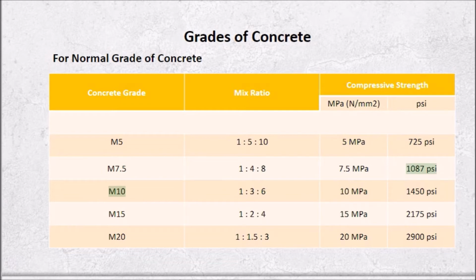M10, 1:3:6, 10 MPa, 1450 psi. M15, 1:2:4, 15 MPa, 2175 psi. M20, 1:1.5:3, 20 MPa, 2900 psi.